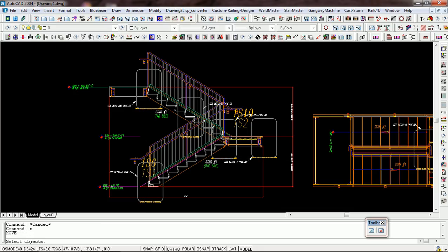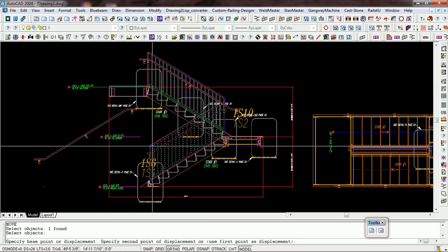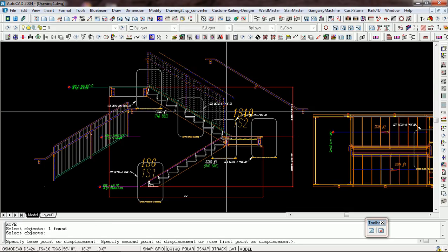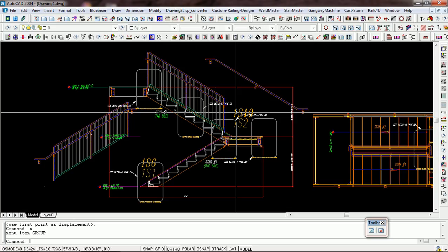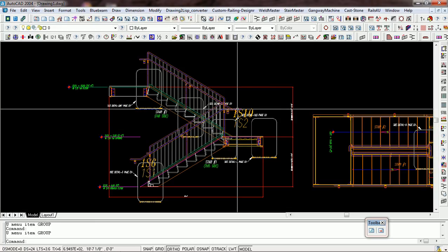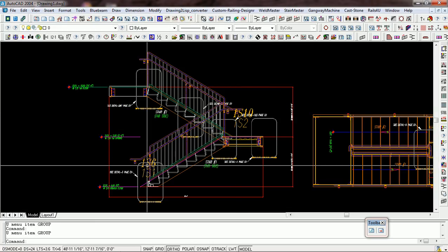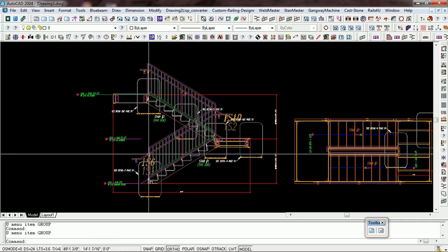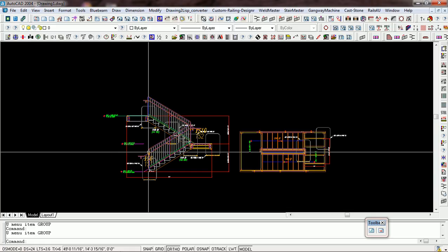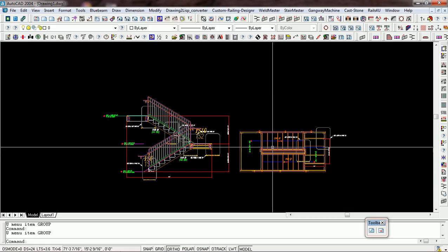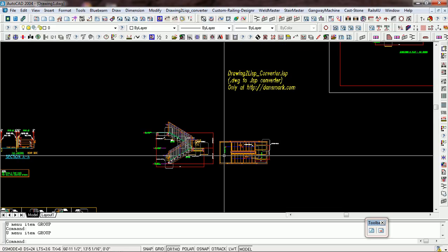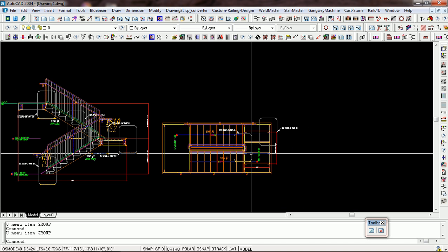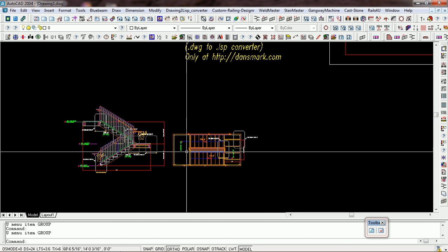Basically we're going to move a railing over here, we're going to move this railing over there, move the handrail and the rail, so it's quickly and efficiently doing this. Yeah, it didn't do the bottom with a hoop on it like you would on a railing, but it doesn't really matter, because I can bring in a hoop, put it on there, put it on my detail, add the material to the bill of material, and I'm done. Put a few annotations on it. A couple hours time I can have this little stair right here completely detailed.